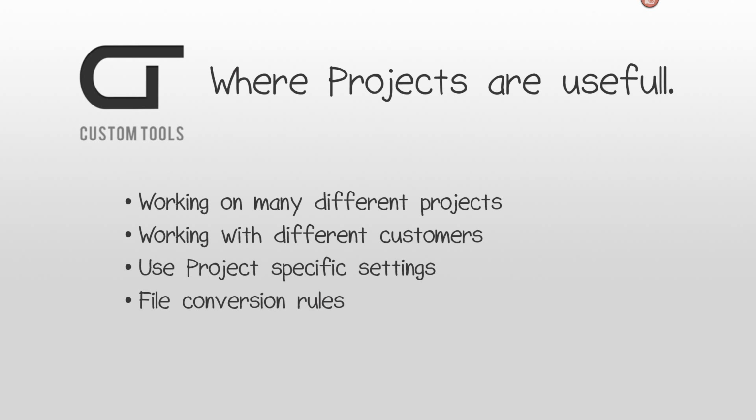First, let's try to highlight why projects are useful in the first place. If you are working on many different projects and each project has to be saved to a project folder, then you should use projects. You can predefine a save location per project and ensure that files go to the correct location in no time. If you have values you always need to define for every file you create, like for instance a customer name, an address, email, telephone number and so on, then use projects. You can define these as default values and only type it in one time when the project is defined. You can set anything as a default value.